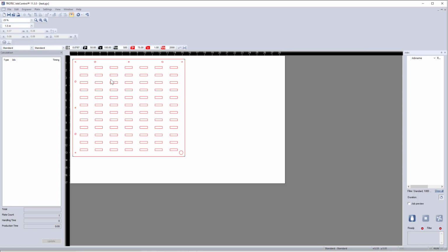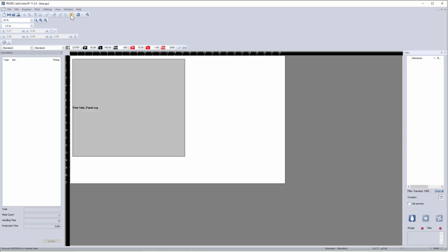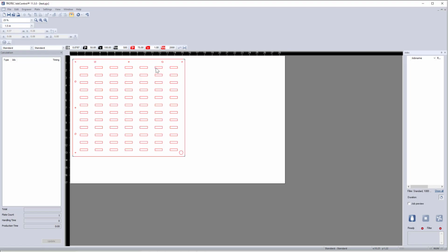In some cases, this view doesn't come in directly. Sometimes this is what you'll see on your screens. If you select this eyeball, this will provide a direct visualization or preview of the components as they will be laser cut. So if I select the actual drawing, you'll see a couple of other things come up here on this left menu, including for the cut parameters or the cut settings, what is the time associated with actually doing the cutting operations for that particular color, as well as information on how much time is going to be required to actually cut it following those pre-programmed laser cutting parameters.